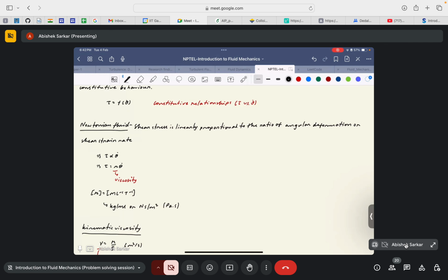Okay, so the final conclusion from the discussion by Professor Chakraborty was that for an ideal case, the Knudsen number, which we initially defined as the ratio of the mean free path length scale over the characteristic length scale of the flow, varies for ideal gases as the ratio of Mach number over the Reynolds number, or Mach number varies as the Knudsen number times the Reynolds number.